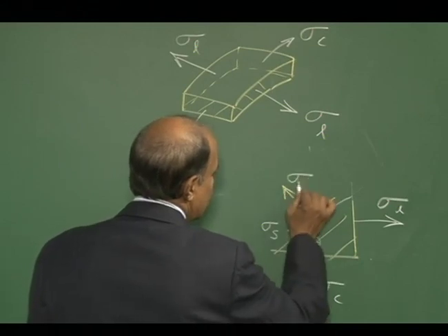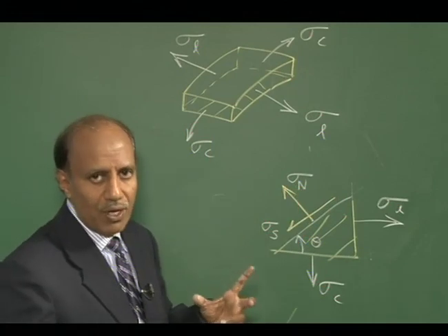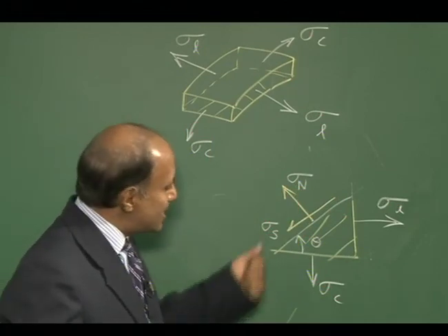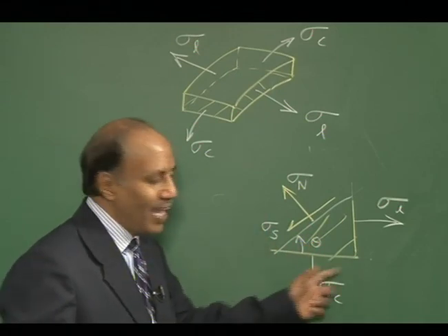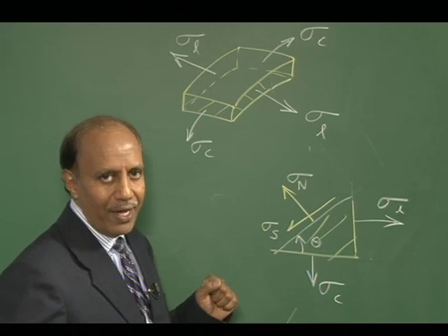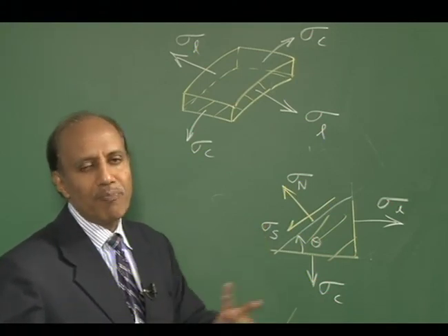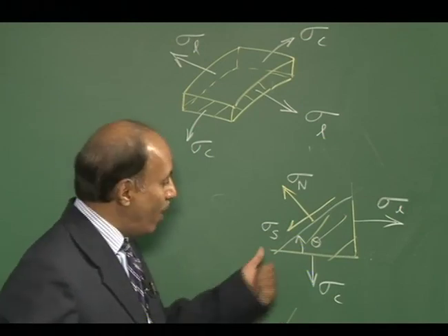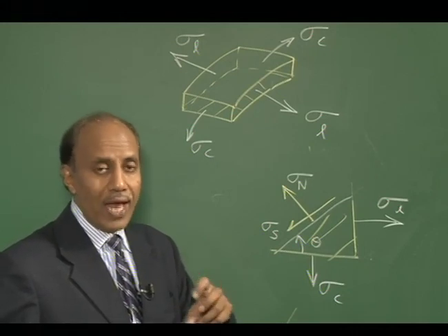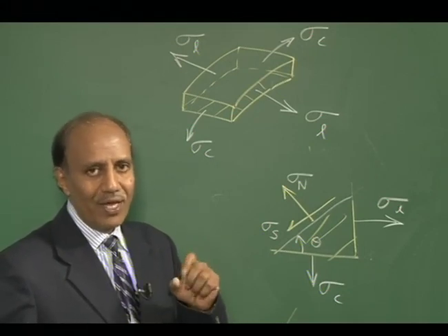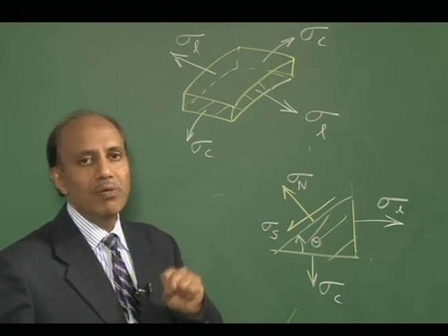So what we are talking about is what may be the maximum shear stress present within the element. That is important because when you are designing, we want this information so that you can design the wall of the cylinder such that the shear stress is within the permissible limit.